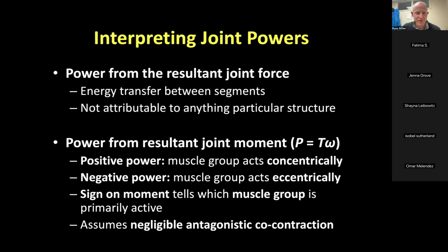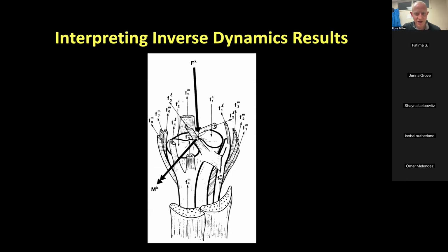Now, to understand this a little bit better, let's go back to my diagram here and ask why exactly we are dropping these things. Notice here, my muscles, everything labeled FM, FM6, FM7, FM8, FM3: these are all forces in tendons of the muscles. Look where those are in relation to the center of this joint. They're a fairly long way away. They wrap around the outside of the joint, meaning, at least in physiological distance, they have fairly long moment arms. So you're multiplying these fairly large forces by these fairly long distances to the center of the joint, getting fairly large torques.